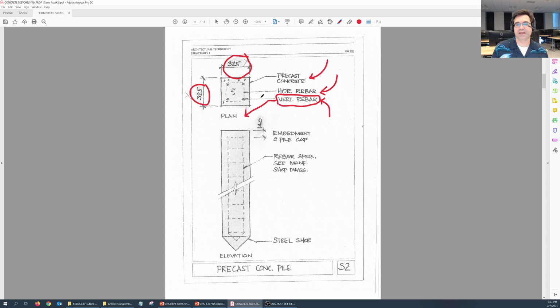Now see here how that's just a straight arrow. You don't want that, so you want to rearrange these so it's always done in that fashion, where there is a note, a horizontal portion, then a leader at an angle, and then the arrow that points to something, not through something. Lovely.